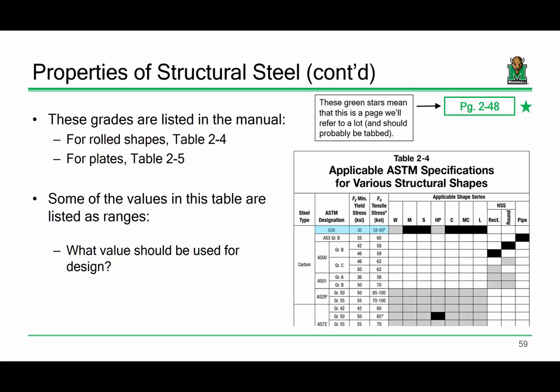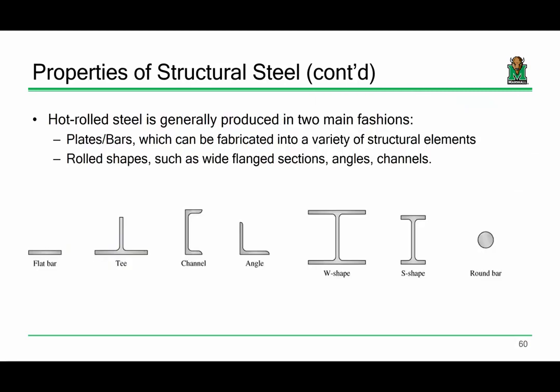So when they report those ranges, it's really for you as the engineer to know: if you're using this in an application where you need ductility, pay attention, because you might not get as much ductility as you think. That's why they report the range. For regular everyday structural design, you'd think just give me the minimum, but that's why. I know it's long and convoluted. They're telling you the range because they want you to know that with a larger FU value, you're getting lower ductility.